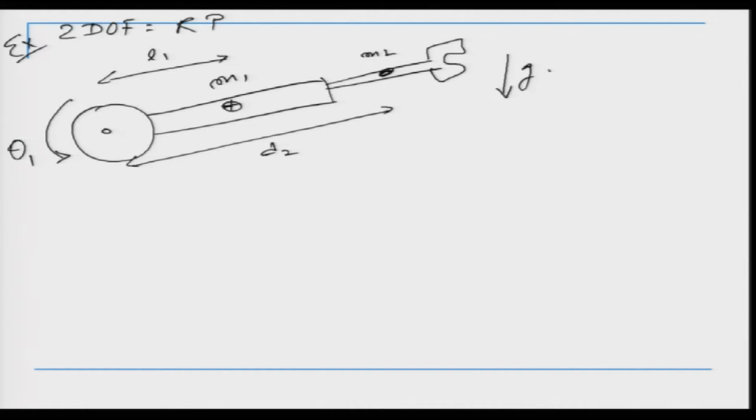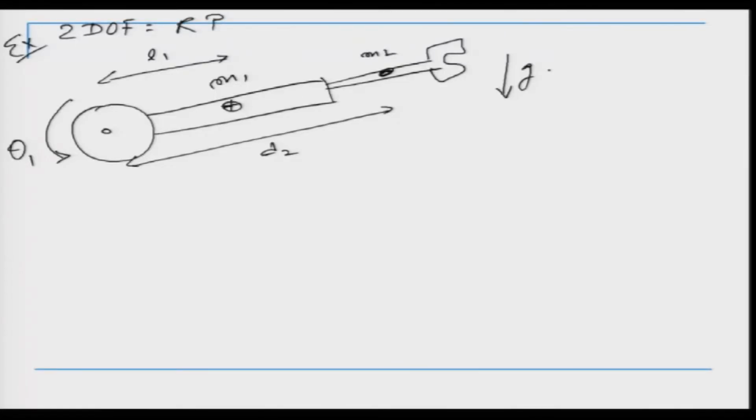Okay. So, the first thing to do is to understand how this manipulator moves. It is 2 degrees of freedom, it has one revolute joint and a prismatic joint. The first joint is revolute and the second joint is prismatic. If I have my arm like this, and this is the revolute joint, this can move like this, but this one is prismatic, so it can slide in and out. So, essentially this is what the structure of the manipulator looks like.